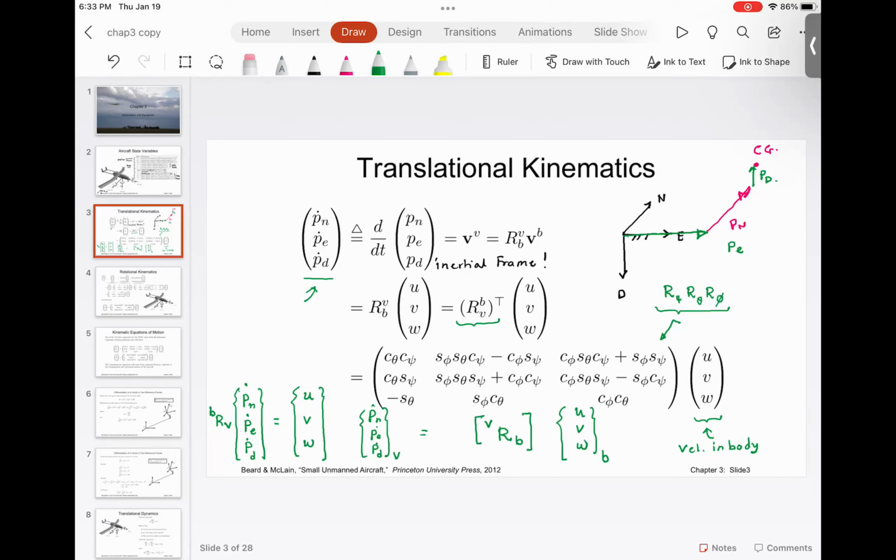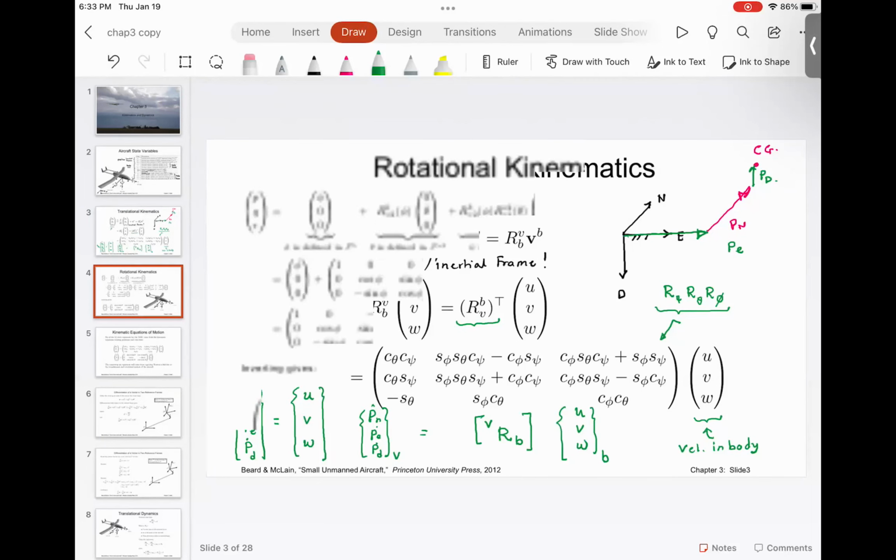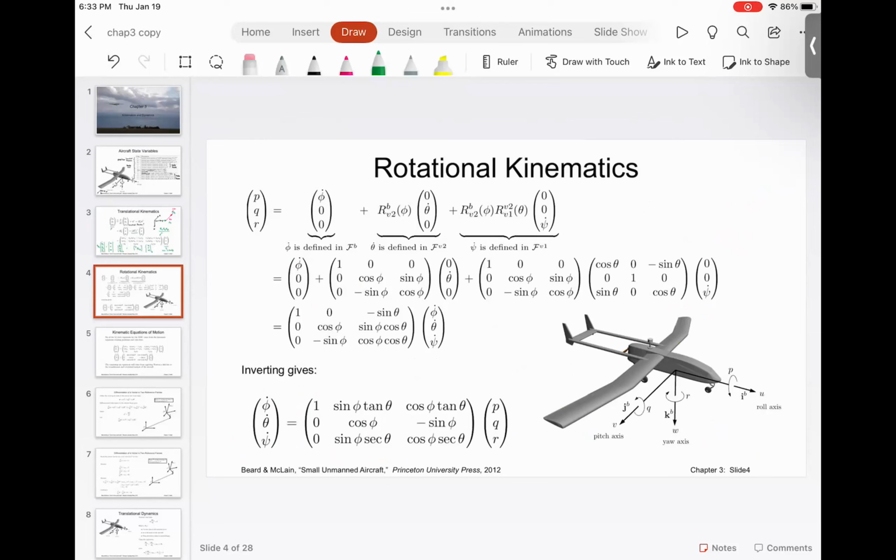And that is basically nothing but the sensor fusion. You have an accelerometer sensor that is not in the same frame. It's giving you some output that is noisy. You integrate that, you find the solution, and use an external reference to correct that solution. So this is the translational dynamics. And please understand, this equation works because the frame is fixed. The frame is fixed. Now, let's talk about the rotational transformation.